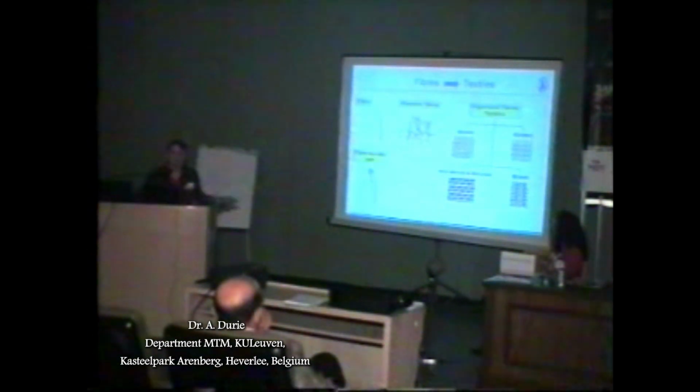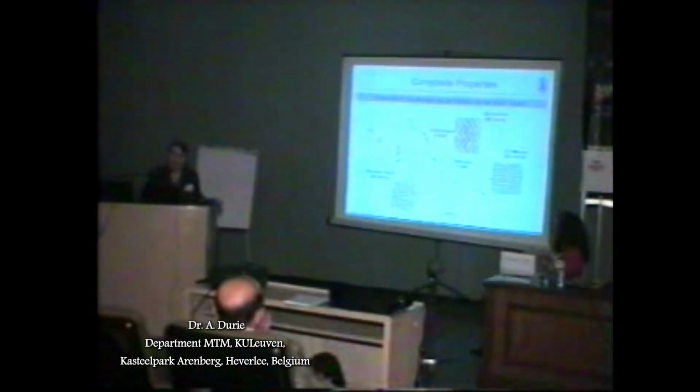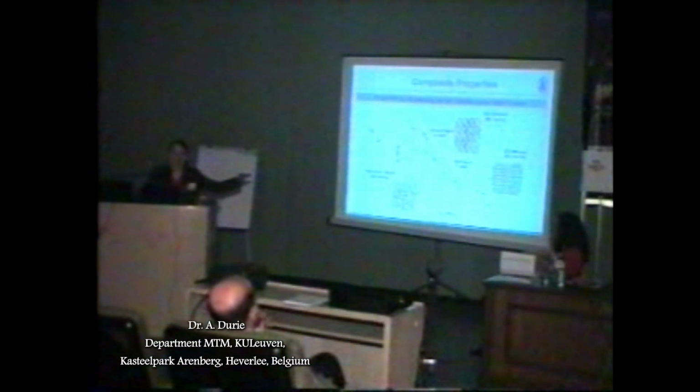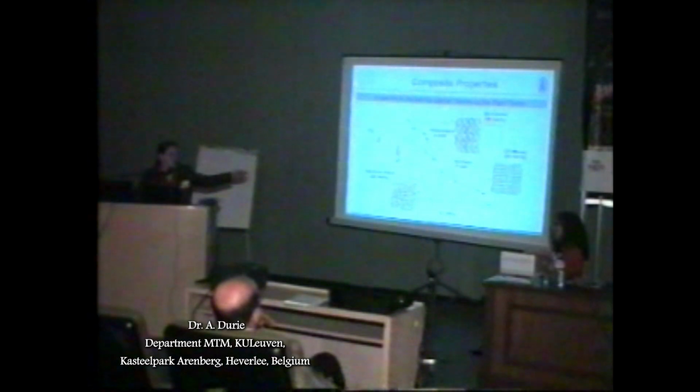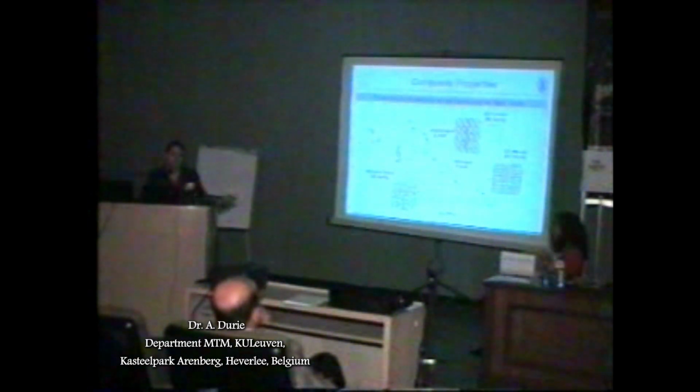Each of these give you different properties. So for example, if we look at the E modulus at different directions, on the x-axis is the E modulus in the weft direction, and on the y-axis is the E modulus in the y direction. Now for example, the small random fibre mat will give you the same properties in each direction, but those properties aren't particularly good. However, these materials are more formable and quite inexpensive relative to other preformed materials.